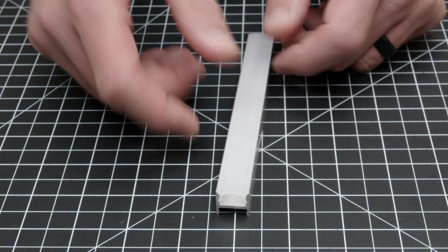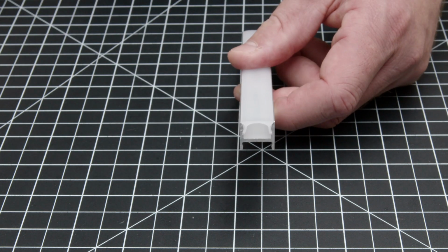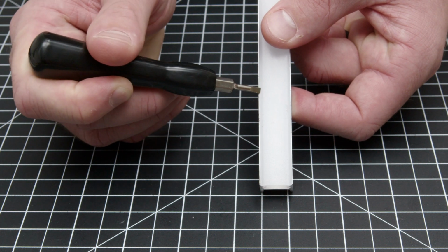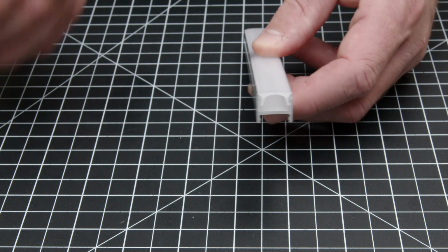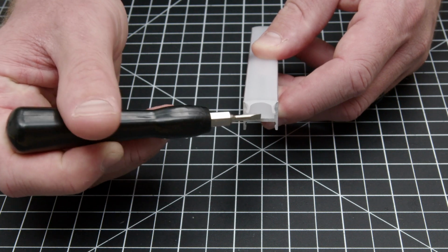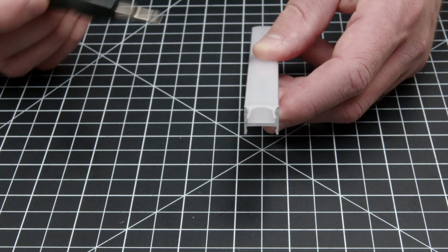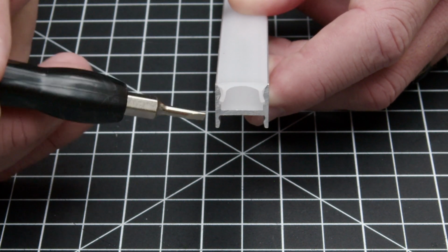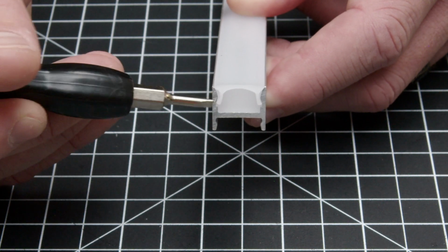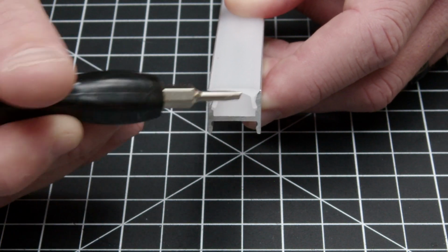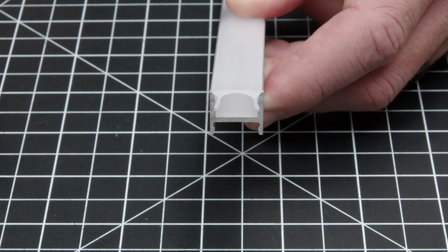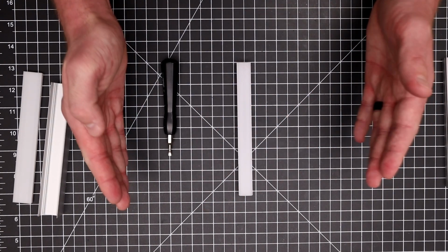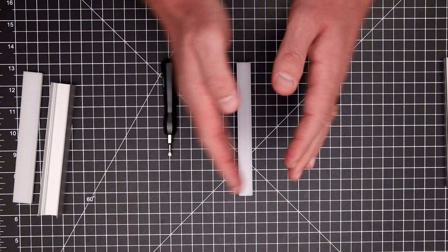And so obviously people ask us, could you make it smaller? The issue is if you want to create homogeneous lighting, so even illumination from one edge of the lens to the other edge, the smaller you go, the more difficult it is because the lens is closer to the tape light. So what we did with the A2 and A3 is notice how the acrylic lens here wraps all the way in to cover the inside of the aluminum. This is not normal. Usually lenses snap on about right here, so there's a bunch of aluminum on the sides that is exposed inside of the raceway. What this allows us to do is cover the aluminum so that the light doesn't die off on the sides, because the aluminum is killing that light.